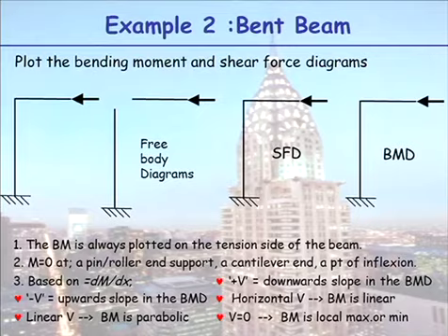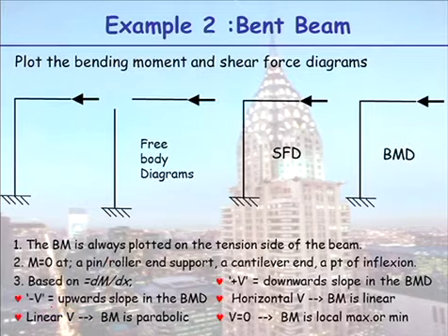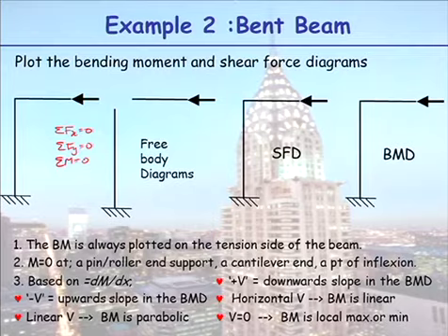So if you don't want to break it up into two free body diagrams, you don't necessarily have to. So let's first work out what direction the reactions are in. Is there a horizontal reaction? There must be, because there's a horizontal force applied. So there's a horizontal reaction here. Is there a vertical reaction?